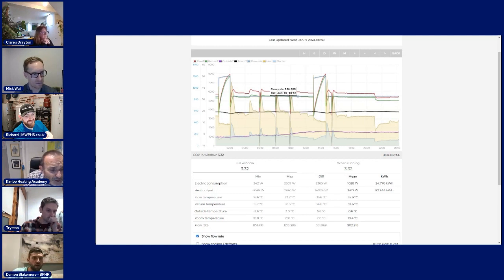I know everyone thinks there's a bit of a weird thing going on with the Vaillant, and me too. We've only done a couple, and I don't really understand what's going on. It's a bit of a head scratcher. But is that because the heat pump is working differently? Let's say, for example, you put another heat pump, a HTN or something, on. Do you think, because the HTN runs at 5 rather than 2 and 3, that those valves would have been fine? And also, do you think it's because the Vaillant has modulation and pump modulation as well? There's all sorts of things modulating that you can't quite get your head around. I've tried to get to the bottom of how they work, because they seem to work in a slightly different way to other ones.